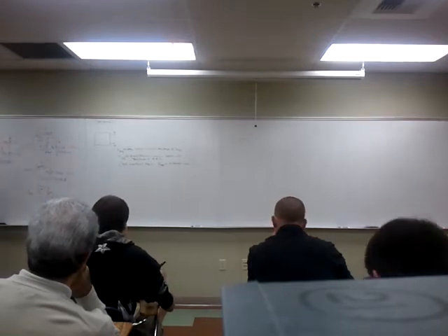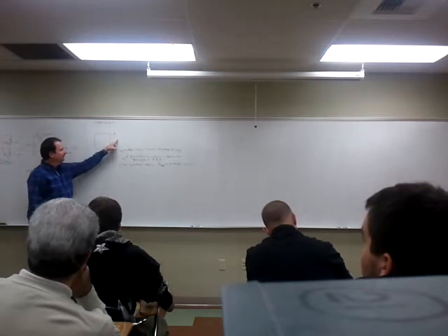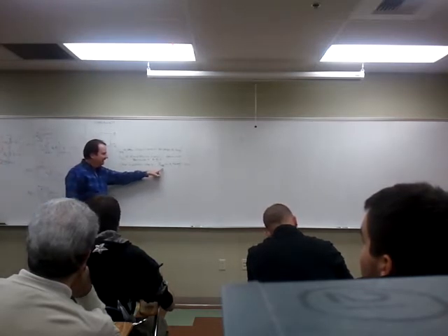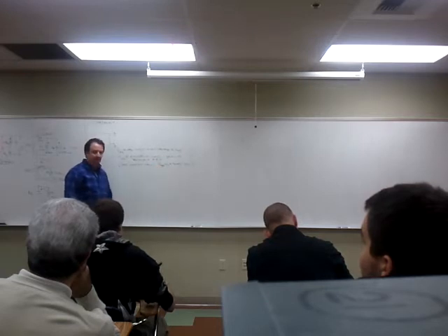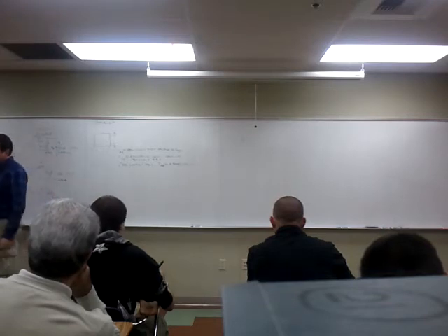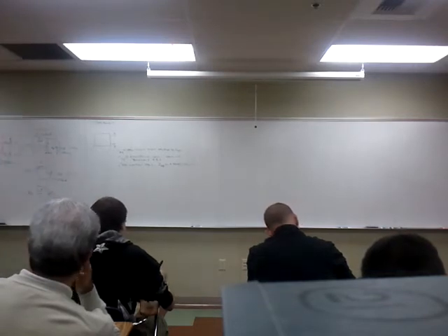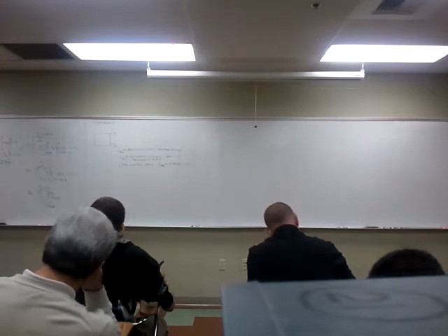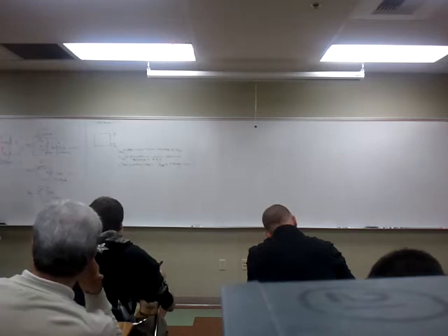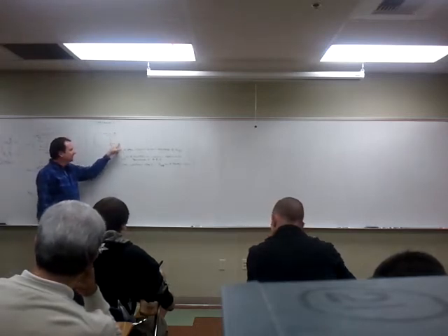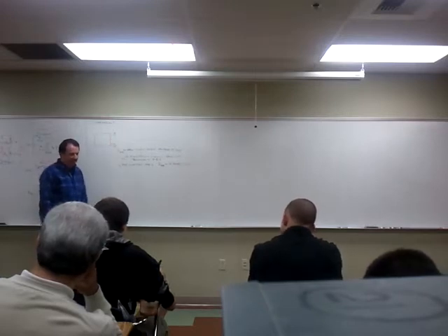But another measurement you could take, couldn't I put a wire here? I could find A to B in a short circuit between points A and B. So if I put a wire here, I could measure the short circuit current. So sometimes that's called the black box theorem, where no matter what circuitry is in here, if I bring 2 points out, I can at least measure the voltage out, the resistance looking back in, and I can short it and measure current.